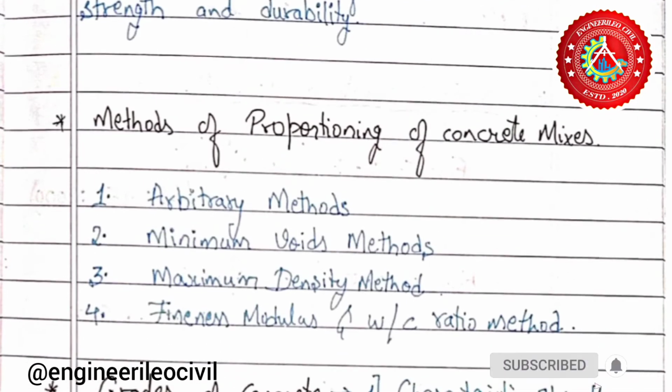Amount of water less than the optimum reduces the strength by 10%. An increase of 10% water above optimum results in a decrease of strength by 15% approximately, while an increase of 50% may decrease the strength to one half. There are various practical values of water cement ratio for structural reinforced cement concrete. Some of them are 1:2:4 concrete for 0.5, 1:1:2 concrete for 0.45, and many more.